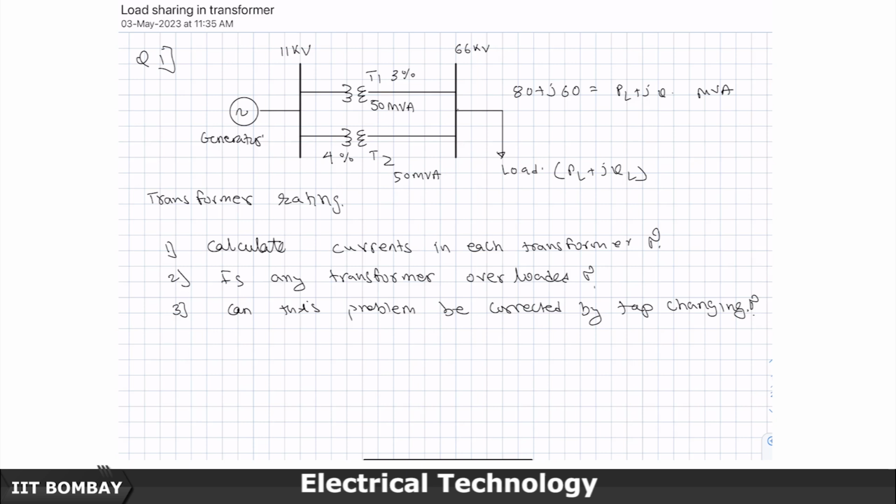And electricity being an essential commodity or supply, the reliability or redundancy is something that is given high importance while designing electrical systems. So, in this case I could of course go for 3 transformers also, there is nothing wrong with that. It depends upon space and other considerations. For a 100 MVA load, I would provision at least 2 transformers. Ideally, even this is not a good thing, because if one transformer fails, I will still have to do around 50% load shedding.